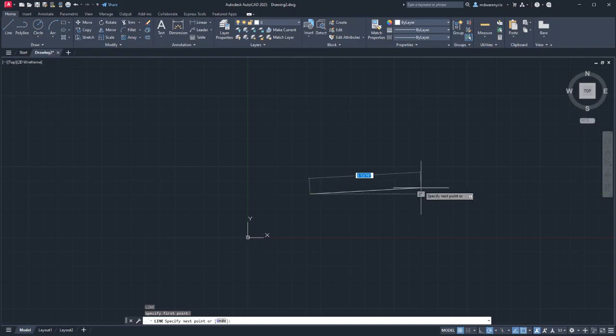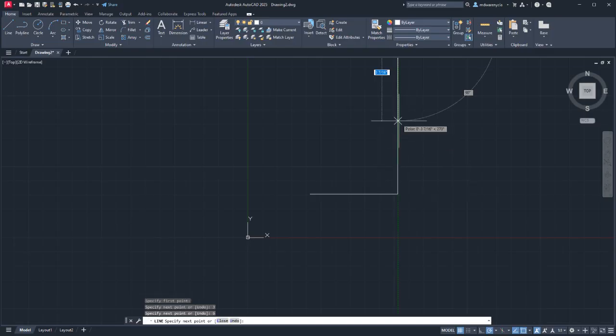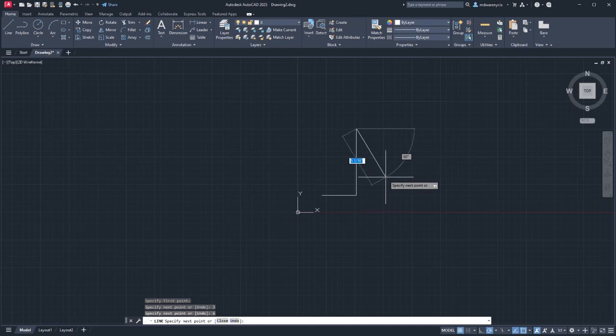But so I can move this off in a direction, and then I can type a value. So say I want this to go 3 inches, 3 enter. And then if I wanted to go up 6 inches, snap it in that direction, 6. If I want it to go in whatever this angle is specifically, I can do 7 in that direction, for example, and just keep going.